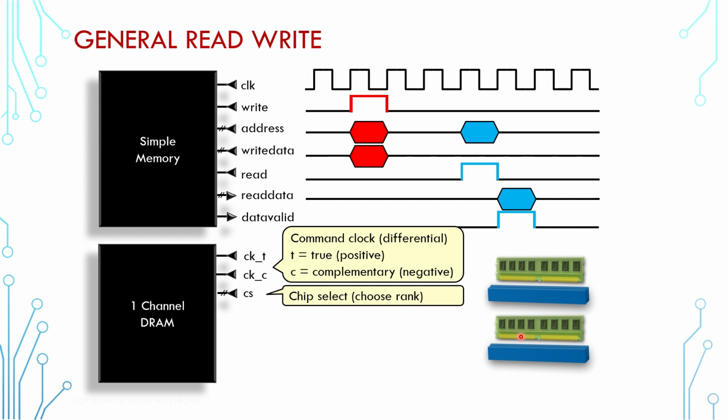If a rank is treated as an address, there would be 2 bits for chip select, and the DIMM will have to decode if an instruction is meant for them. But DIMM doesn't have a decoder. If you purchase a DIMM, you can insert it at any memory slot. A DIMM is unaware of which rank it is assigned, and therefore it only makes sense that every rank has a dedicated chip select signal.